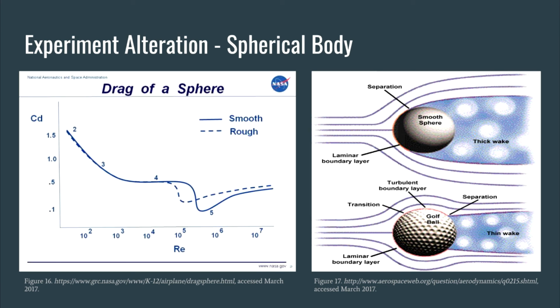The surface roughness would have an effect on whether the flow is symmetric. Slight variations in the roughness of two opposing sides, as well as any imperfections in the sphere, will create an uneven flow field. This is not as much of a problem in a cylinder because the flow only passes above and below the cylinder. The sphere would have to be symmetrical all around in order to create a symmetrical flow regime.